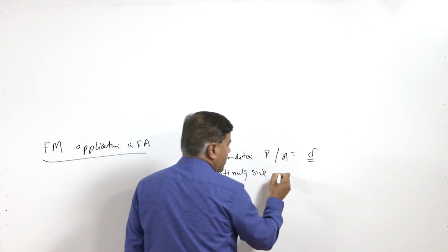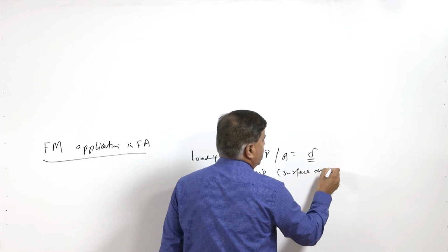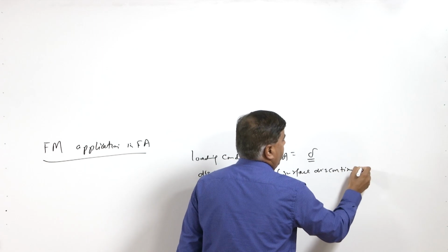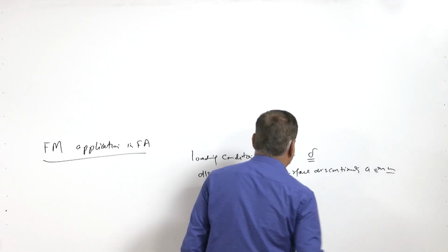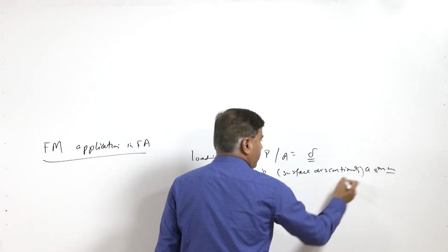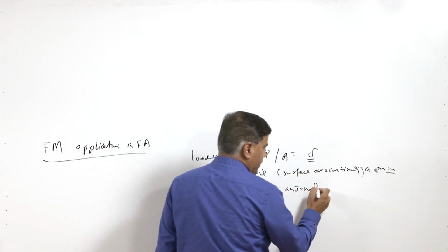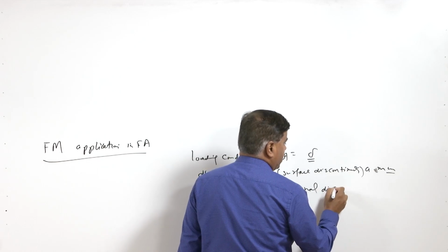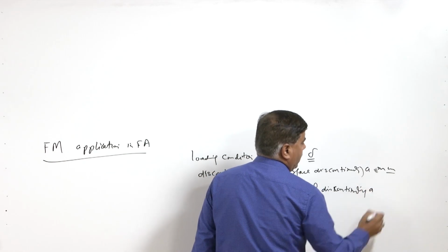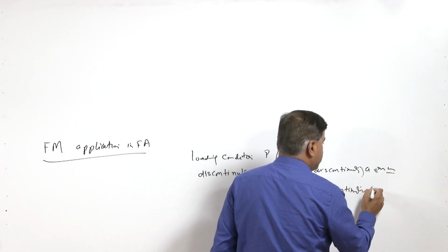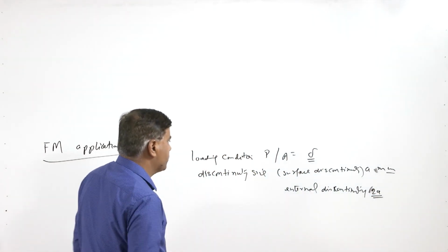Say the discontinuity size for surface discontinuities is A, and it is mostly expressed in mm, and for internal discontinuities, which are within the surface, the discontinuity is taken as 2A. Because in the final equation we use basically A only.